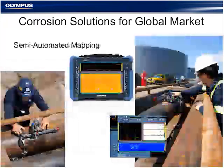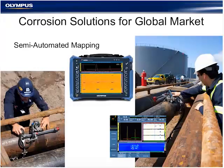Moving from there, you can get into more sophisticated solutions where you can provide much more thorough mapping of an area. This is an example of a semi-automated mapping system, oftentimes now using phased array instead of a conventional dual element transducer. And we're using some sort of scanner to hold that phased array probe. So we have a chain scanner in this photo here in this application example. In this chain scanner, just like in the B-scan example where it's recording position information along the length of the pipe, the chain scanner is now a 2-axis encoding device. So it's reporting back to the instrument and correlating the thickness data along 2 axes.